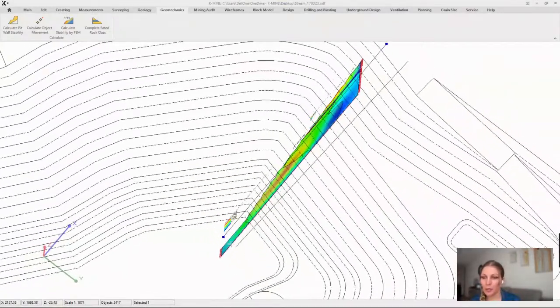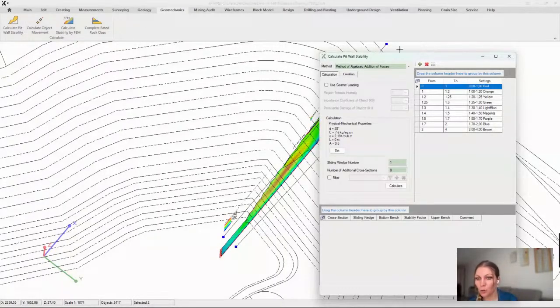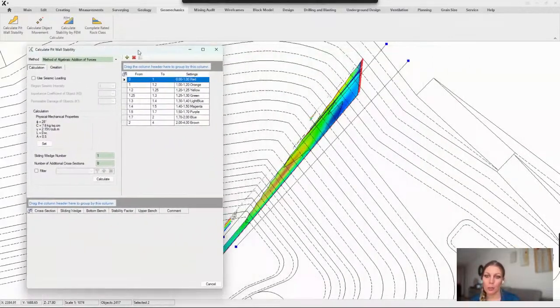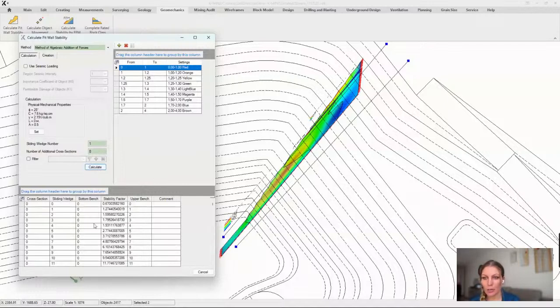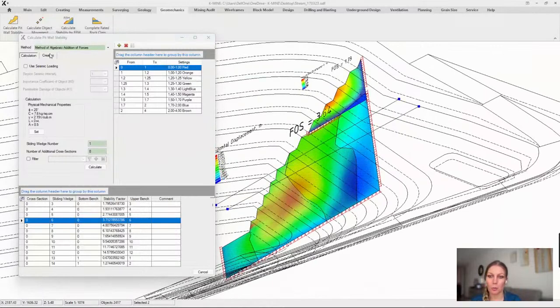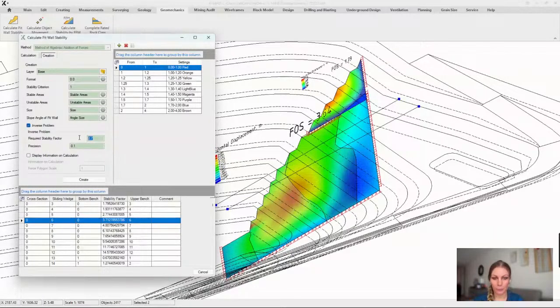We'll pick the prism that connects the 0th and 6th ledges from the result list. And then we'll input the required safety factor, like 2.7, in the required stability factor field and run the calculation. Using this approach, we arrived at a stability factor of 3.7, which closely matches the factor derived from the FEM method.